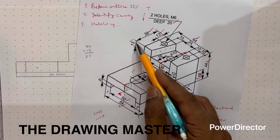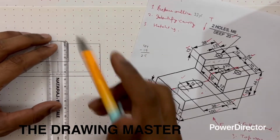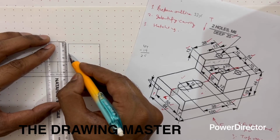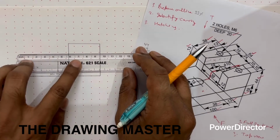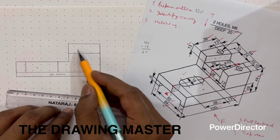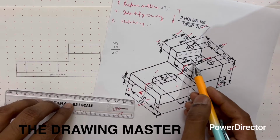So this height is 13. This height is 13. So take a point at the distance of 13 mm. This is 10, 11, 12, 13. Now this is unaffected area. This area has no effect of the cutting plane because the cutting plane is cutting the object at center.